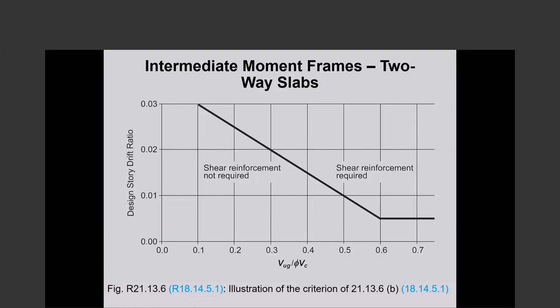The design story drift, I think we went into yesterday. The deflection at the top of a story minus the deflection at the bottom of the same story under the design earthquake forces. Okay, the earthquake forces that are prescribed by ASCE 7 and BNBC 2020. Now, that is design story drift.